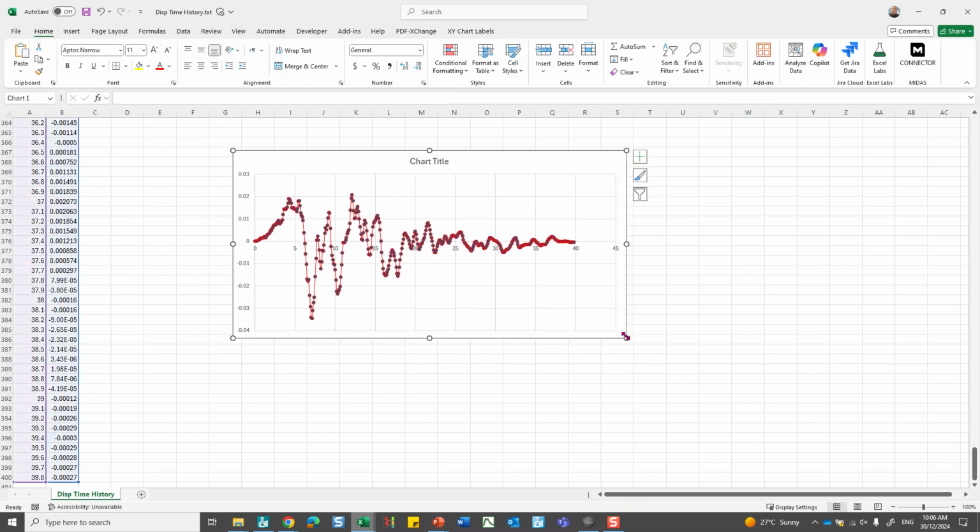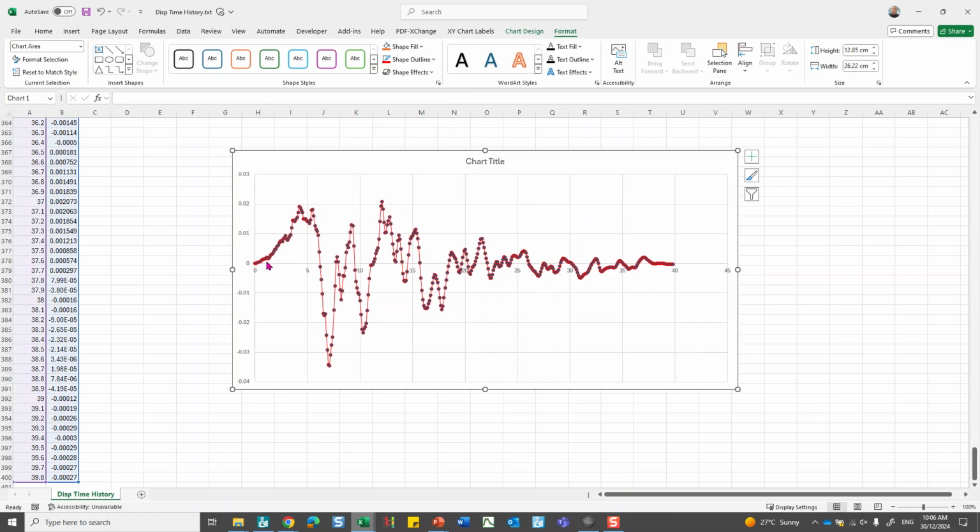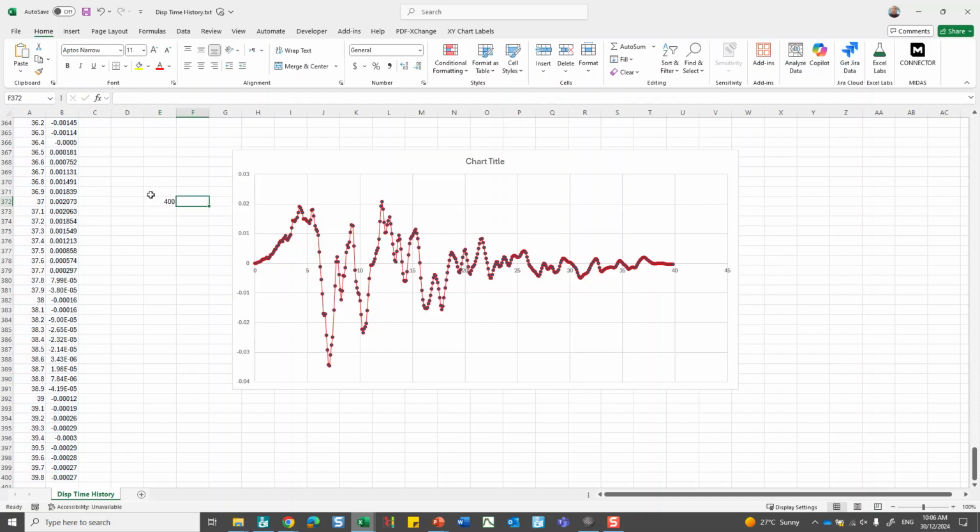So what happens here is, now if we have used 400 points, it means that when PLAXIS does the explicit time integration, it basically follows each point of those to cover the 30-second or the 40-second we're applying. Now imagine, because I'm using 400 steps, that PLAXIS will follow this more or less closely. Now, if I use, for whatever sake, only 20 points, this is what PLAXIS will do.